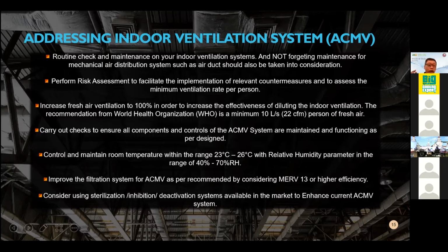They also recommend Airstream, CDC, WHO. They recommend considering MERV 13 or higher efficiency rating. Okay, MERV is minimum efficiency reporting value, just the long form, just to explain to you. So the third one, when they mention the DOSH guideline, okay, consider using a sterilizing or inhibition or deactivation system available in the market. This is very important to enhance the current ACMV system to deactivate any viruses or bacteria or microbes, right?